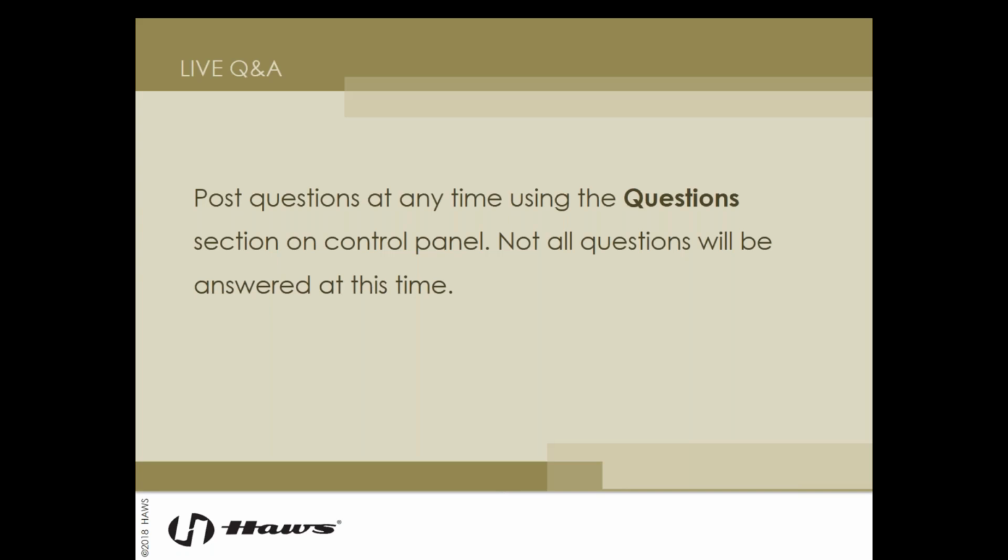Thank you, Kelly. We're going to take one more question, and then the next slide will have contact information for you guys as well, so hang tight. Is there a specific requirement for the type of actuation of a drinking fountain or water cooler? For example, push button, lever, or sensor? No, actually, the ADA requires only that there be no twisting of the wrist or grasping of the hand. You should be able to either push the button, press down on a lever, or activate a sensor operated mechanism. It doesn't make a preference.